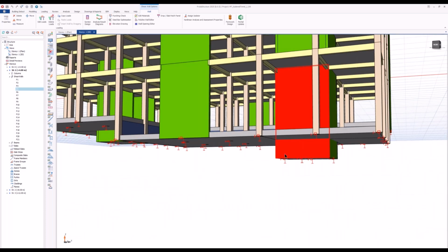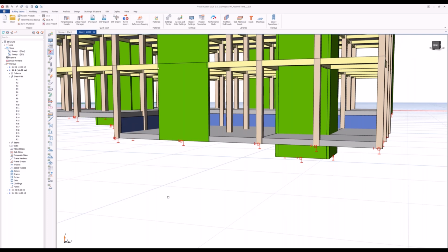And for this wall, let's check the properties. The top is not dropped. The top is sitting at the Storey 1 level, and the bottom edge is dropped by 380 centimeters. In this way, you can easily define the step foundations with different elevations. Okay,